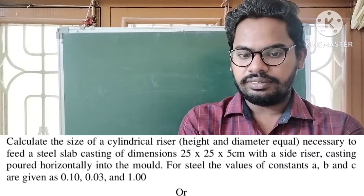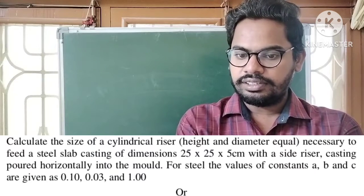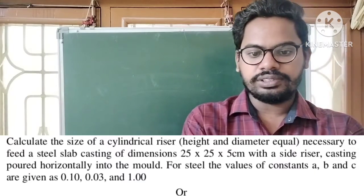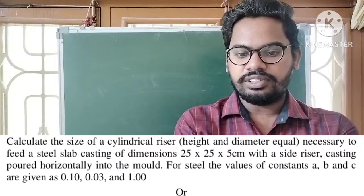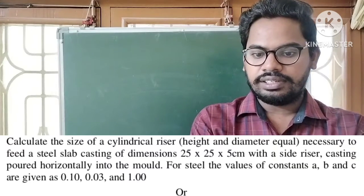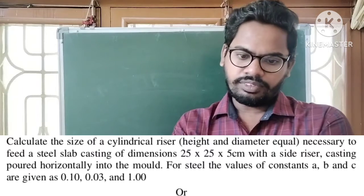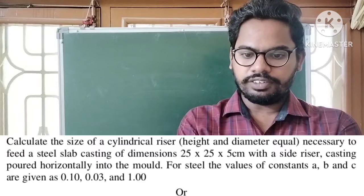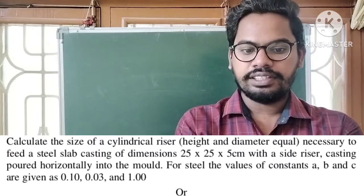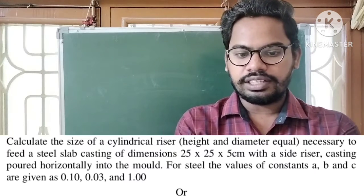Calculate the size of a cylindrical riser, height and diameter equal, necessary to feed a steel slab casting of dimensions 25 into 25 into 5 centimeters with a side riser. Casting poured horizontally into the mold. For steel, the values of constants A, B and C are given as 0.10, 0.03 and 1.00.